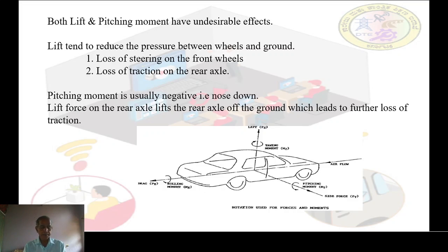I'll explain the axis forces. Capital Px is equal to the force of air drag in the direction of motion with wind along the longitudinal axis. Py, the y-axis, is equal to side wind force or cross wind force. Third, Pz is equal to lift force.